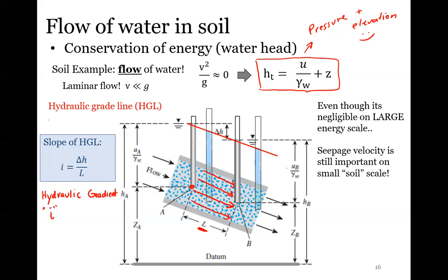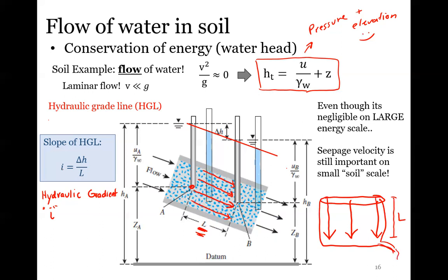So if you have flow going vertically, like if you have that big container of soil again, and we pour water at the top and the water trickles down, then the length is going to really be a height. So always think of it that way. It's not necessarily lengthwise, like horizontally, it's just the length of the flow lines. In this case, this could technically be the length too, like if we had some bucket of water and it's flowing out there.